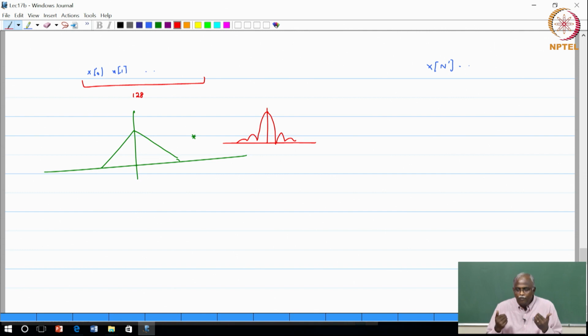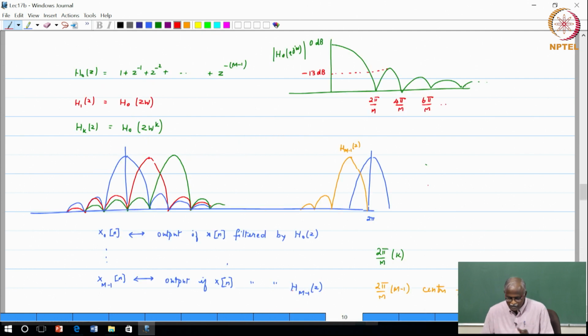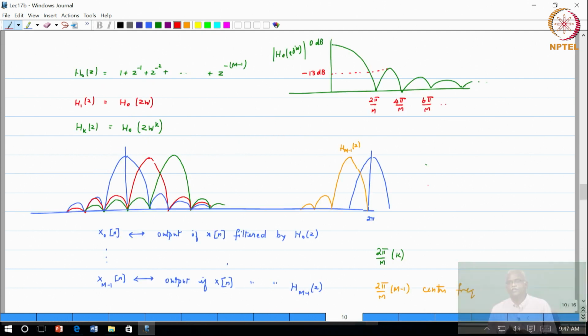So, the way I want to look at it is from a filtering point of view, instead of doing a rectangular window followed by a DFT, then sliding my data, doing another DFT, and going through the process to obtain my spectral estimation. What we are saying is, hey, by the way, this is the same as passing it through a filter bank. So, you can take your data, not need to window it, just pass it through a rectangular window based filter bank. This type of filter bank is exactly what your DFT is also effectively doing. Okay.